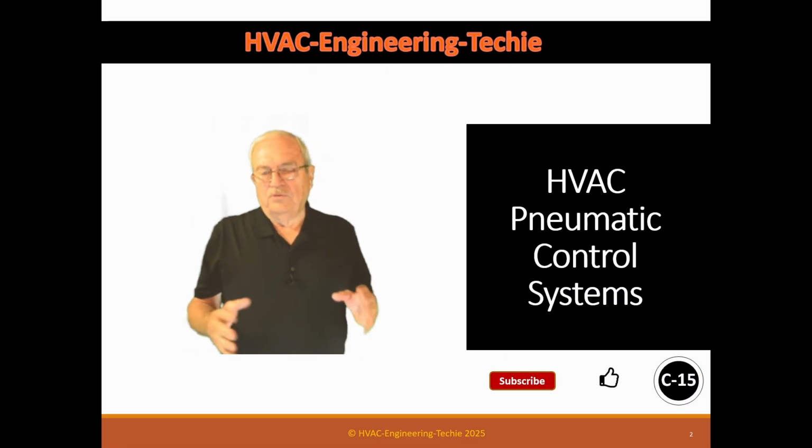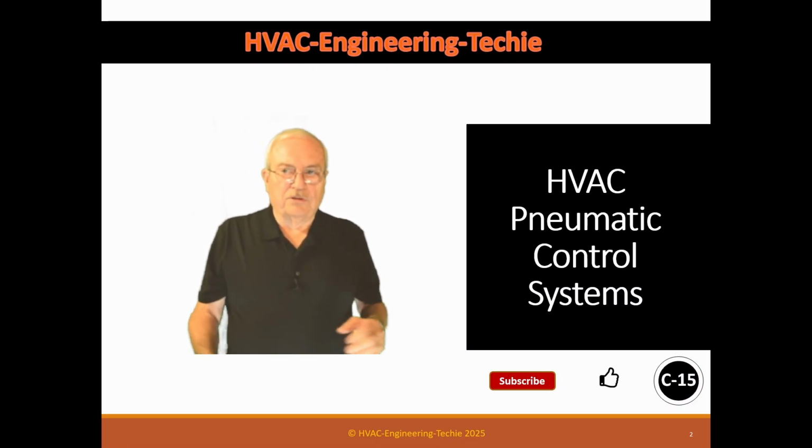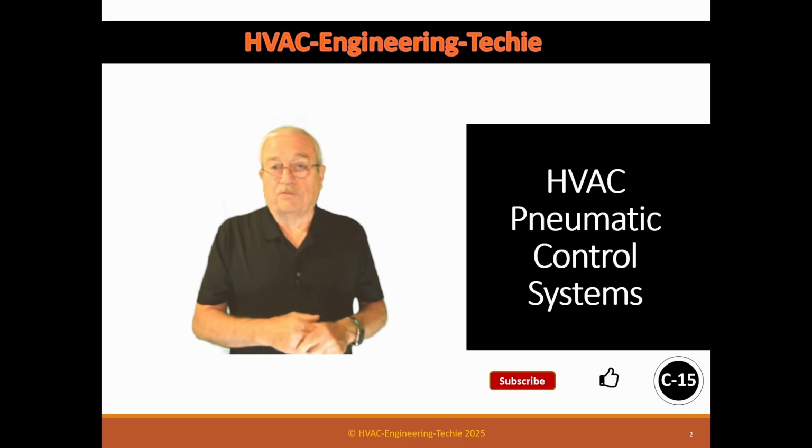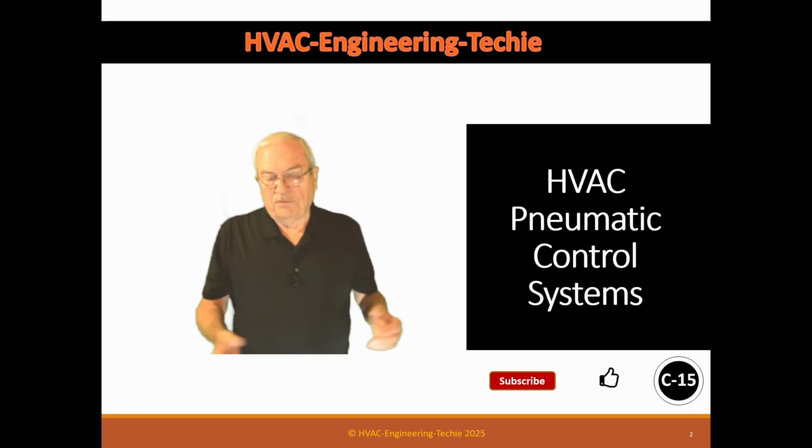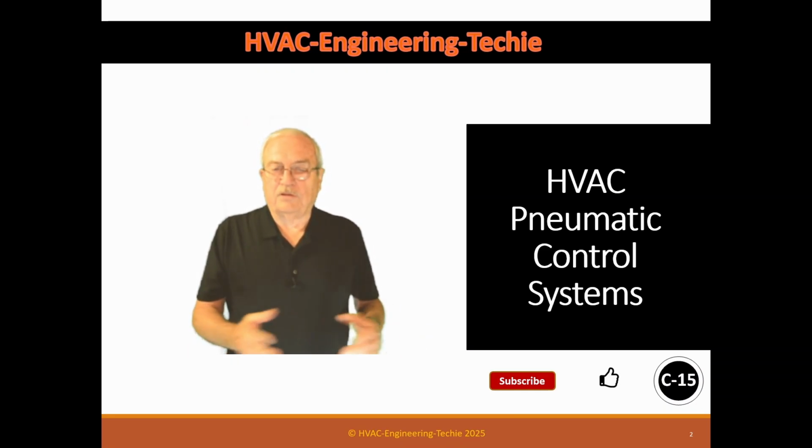Now, we don't use a lot of pneumatics like we used to, but we still use them for overlays to push stuff around like valves and dampers. And we use them for explosion-proof atmospheres. It works well there too.